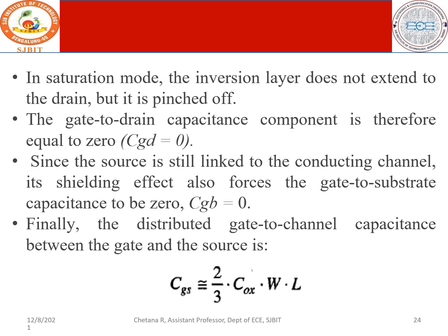But still the source is linked and it is conducting, but it is not reaching the complete drain terminal because it is pinched off. Only a limited current flow occurs. In spite of increasing your gate voltage and the drain voltage, there is no impact on the current. That is why we call it the saturation current, the same amount of current flows.